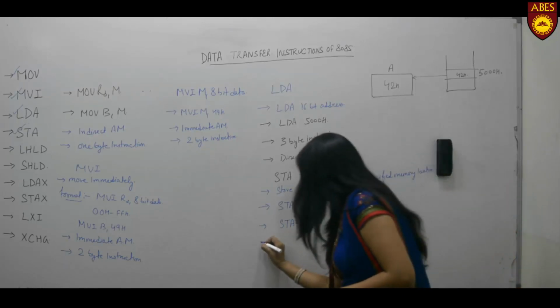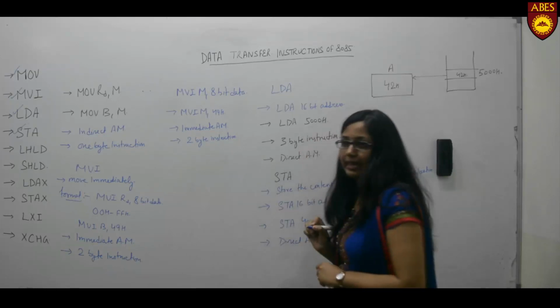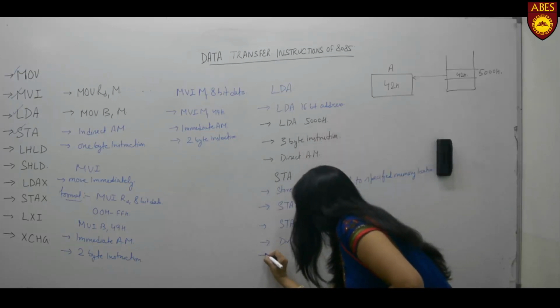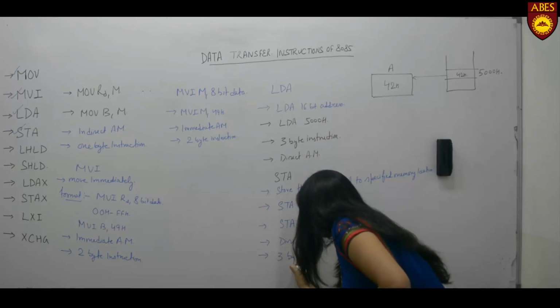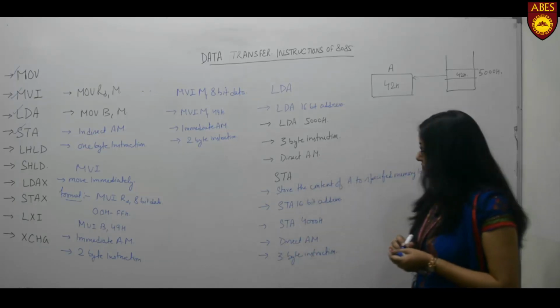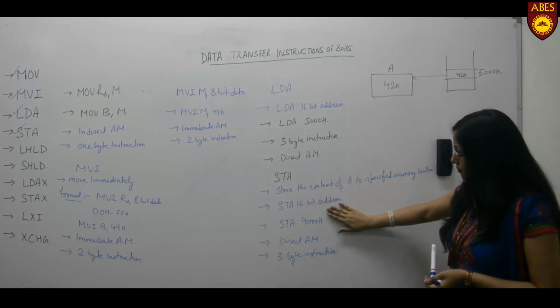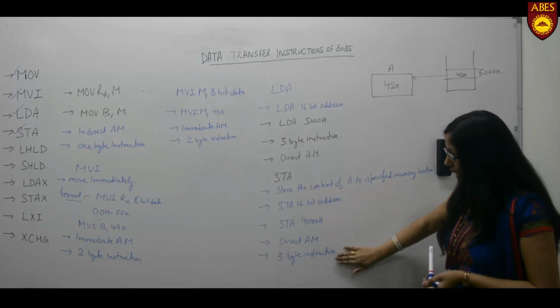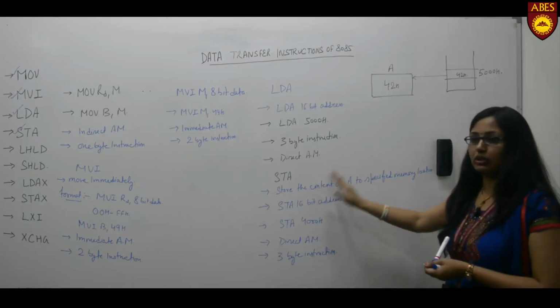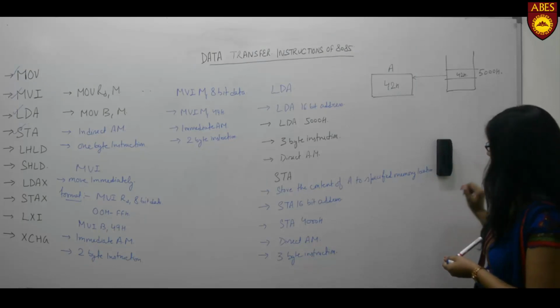This again belongs to the direct addressing mode, and this instruction is a 3-byte instruction. This is all about STA.